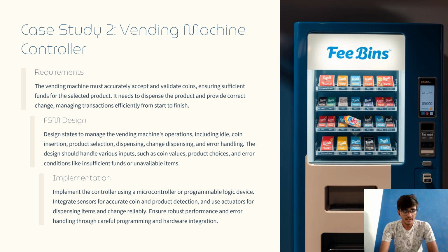FSM design. Design states to manage the vending machine's operations, including idle, coin insertion, product selection, dispensing, change dispensing, and error handling. The design should handle various inputs such as coin values, product choice, and error conditions like insufficient funds or unavailable items. The fourth one is implementation.